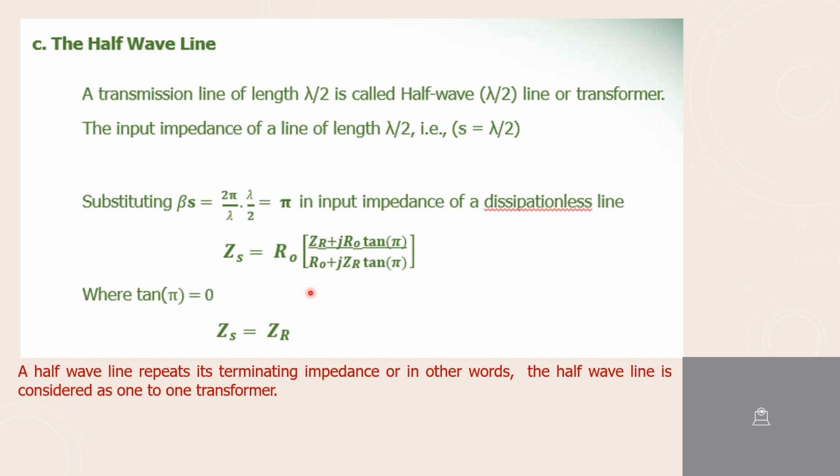So likewise, we are able to match the source impedance with the load impedance. By matching both source and load impedance, we can achieve the maximum amount of power being transferred from the source to the load. So that is the main aim of impedance matching.